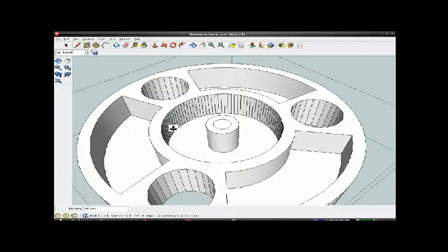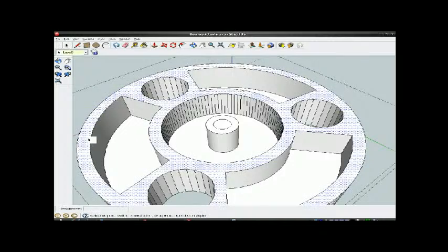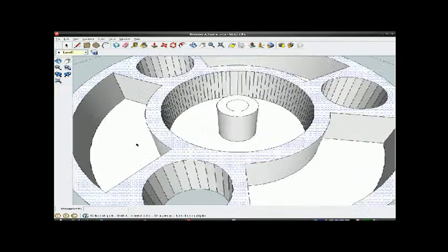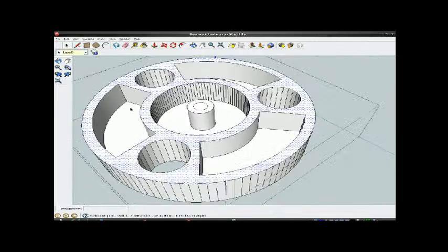You can set it to have, say, honeycomb on like 60% infill or 30% infill, but the reason why I don't want to choose that is because it tends to leave all the structural parts full of holes as well. So I want the structural parts to be solid. I just want some great big voids in the middle to save me plastic. So it's just easy to do it like this.